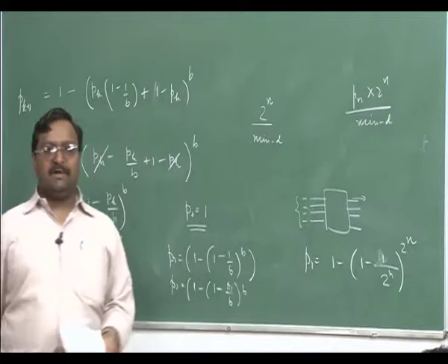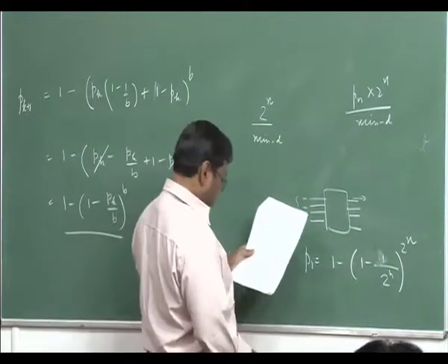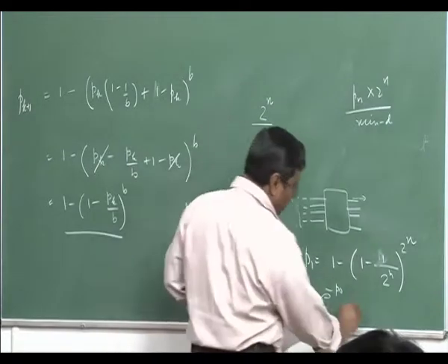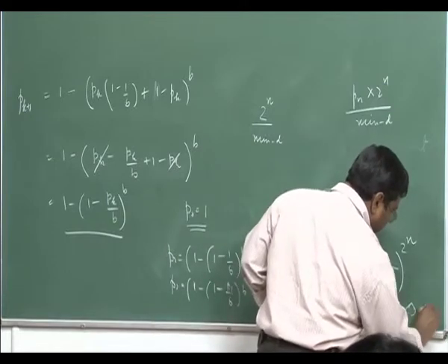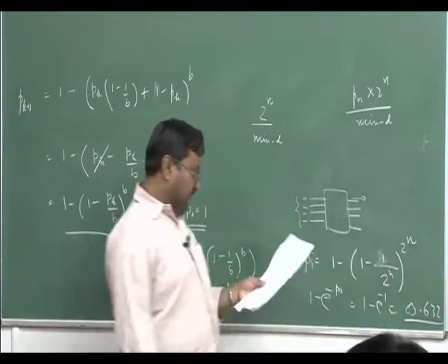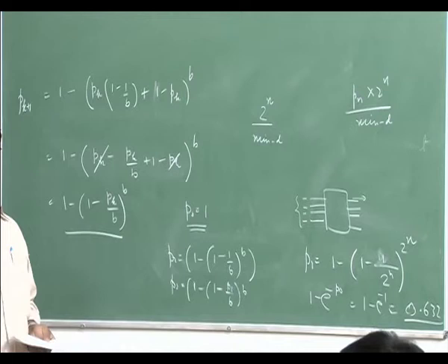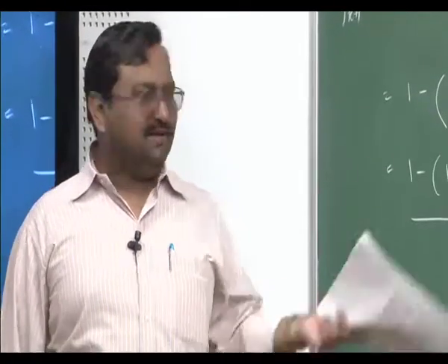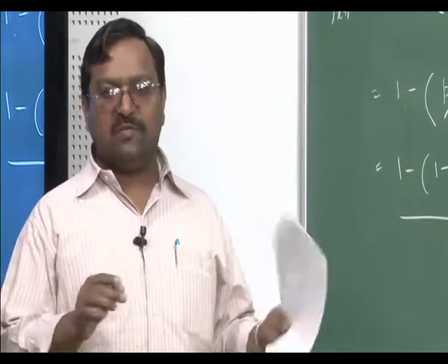And of course, when n becomes very large, 2 raised power n becomes very large, this can be approximated, so with P0 put to 1, you get 1 minus e raised power minus 1, which is 0.632. So that is the maximum throughput which you can achieve with a single crossbar. Is the whole switch implemented using a single crossbar, or am I implementing it using multiple crossbars by creating a delta network? Yeah, there is one single crossbar being used for the whole switch.